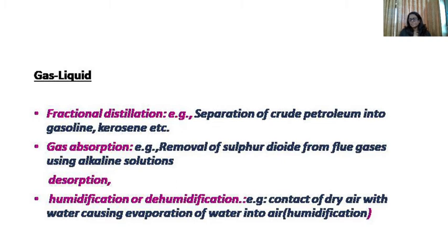First one is fractional distillation or simply distillation, an operation where a liquid mixture is subjected to separation by the use of thermal energy. That is, the given liquid mixture is heated so that vapor is produced to create another phase. The vapor and liquid phases are then contacted in a suitable manner so that the vapor gets enriched in a single component which can be taken out as a product.